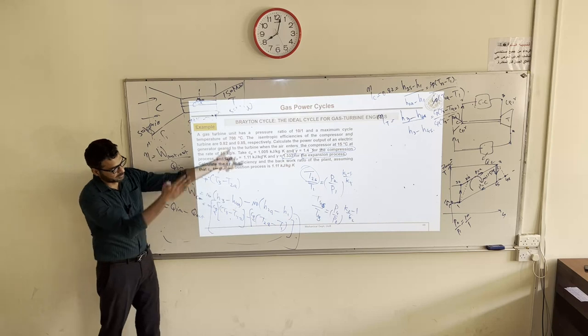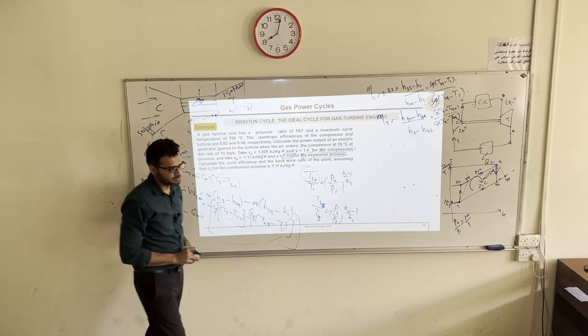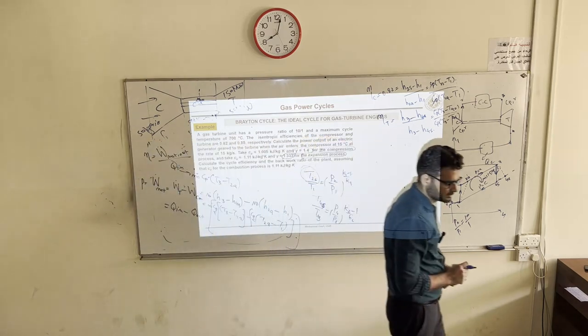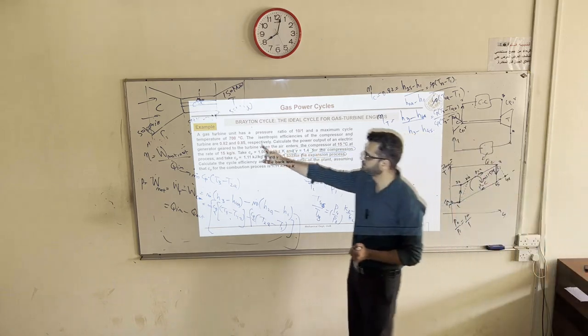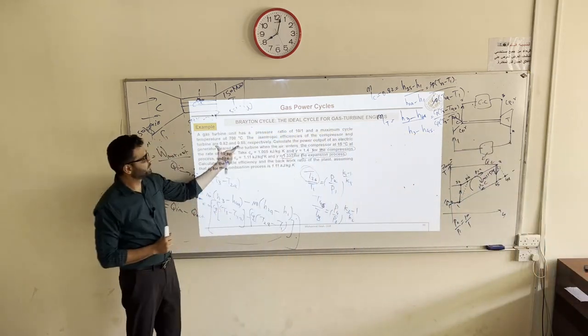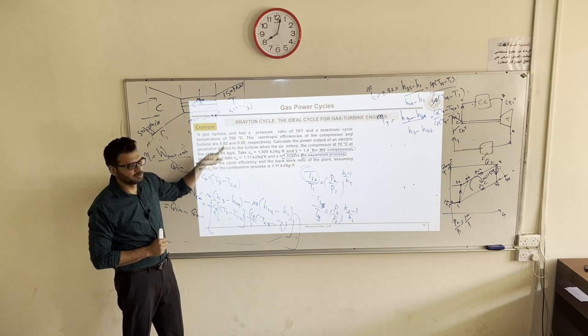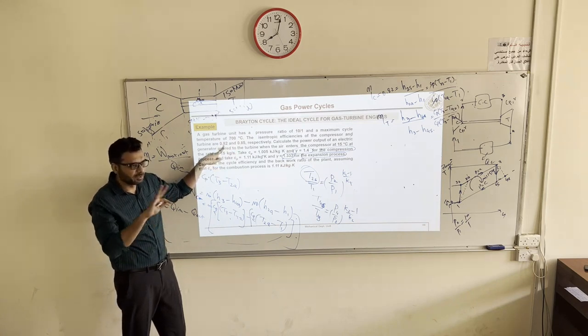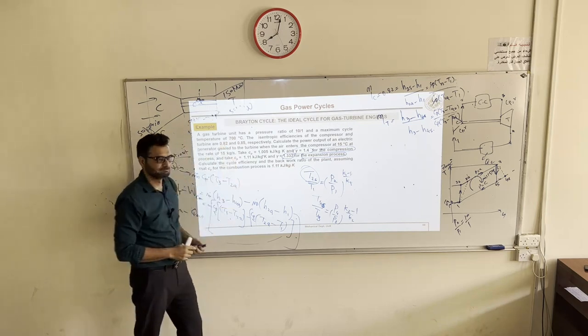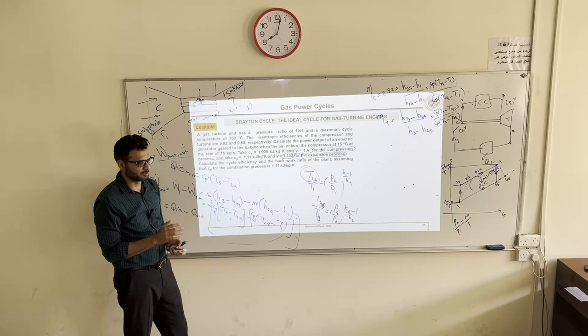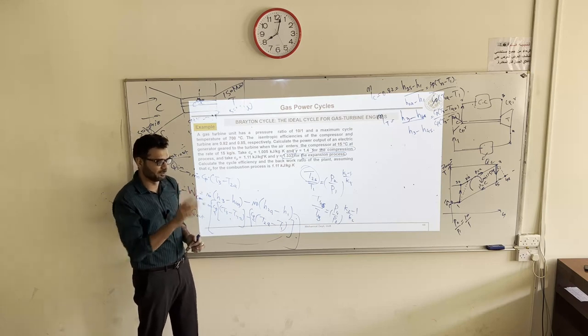Yes, actual points. Isentropic is only used to calculate actual ones. That is the usefulness of this concept of isentropic. If you do not have this, look, what you are saying in compressor, you are saying maximum irreversibilities or friction losses should not be more, so you are assuming a good compressor should not have more than 20% losses.